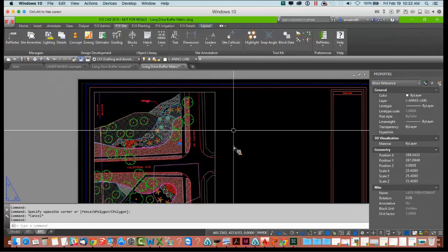We're going to move on as well with this into some more advanced things. I hope you guys got a handle on the basics of how scale is working between model space and paper space, and how, as long as you set the scale correctly and make sure your units are correct from the start, it's set and forget. However, let's see if we have any questions on those basics so far in the meantime.